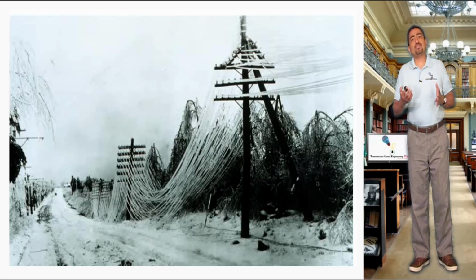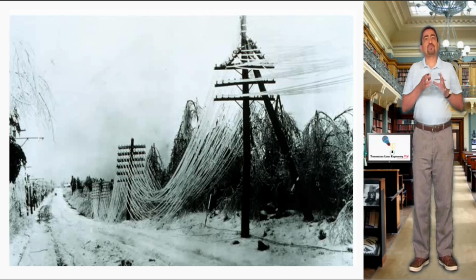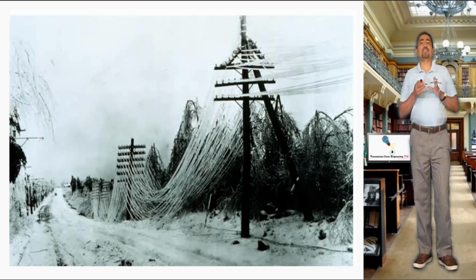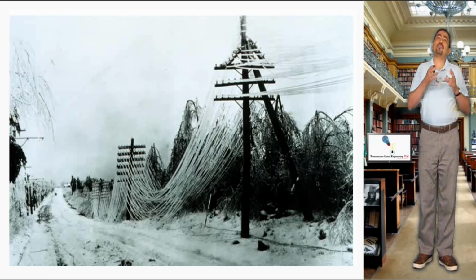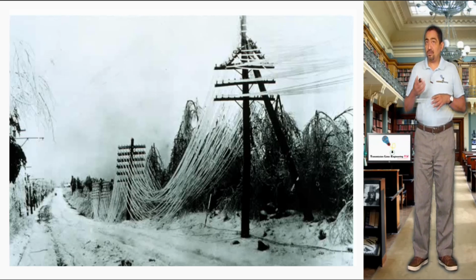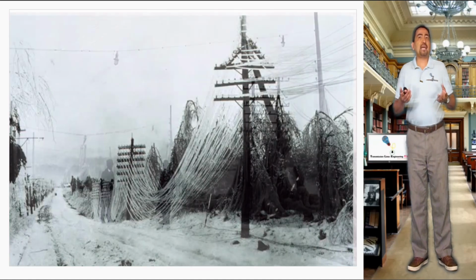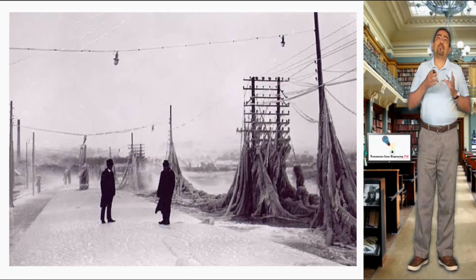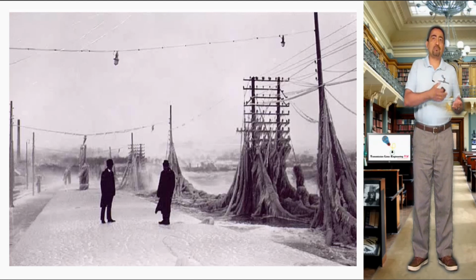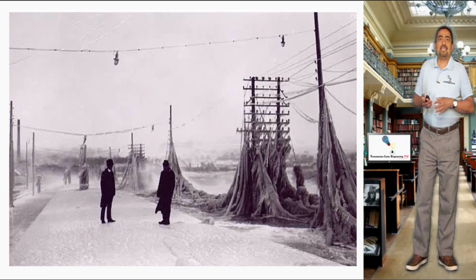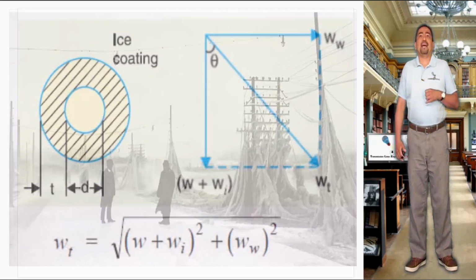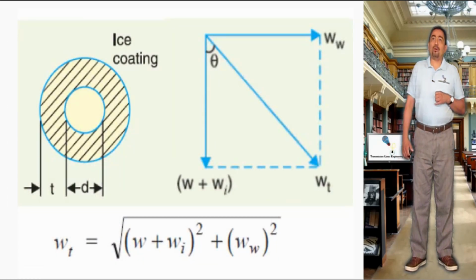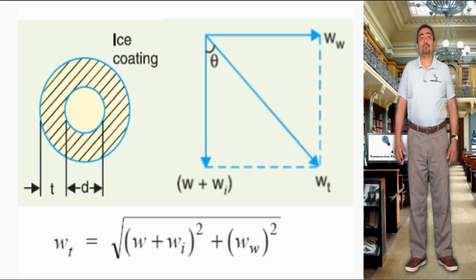So this is the reason why both transmission lines and other disciplines follow non-linear analysis methods nowadays. At the beginning of the 20th century, it was observed that in the first transmission lines, accumulations of ice were generated on the conductors, causing a sag increase, and therefore more frequent ground faults or faults between conductors were encountered. At that time, the concept of ice overload on conductors was discovered and developed as well.